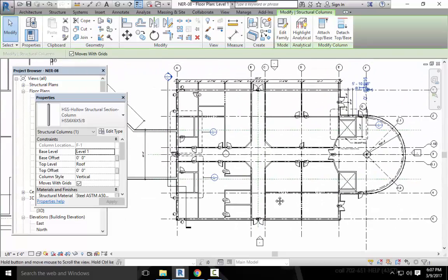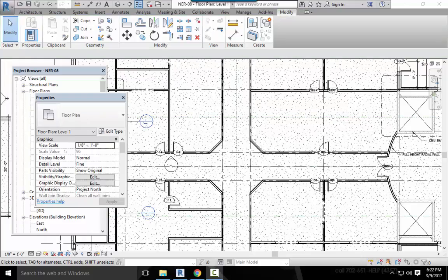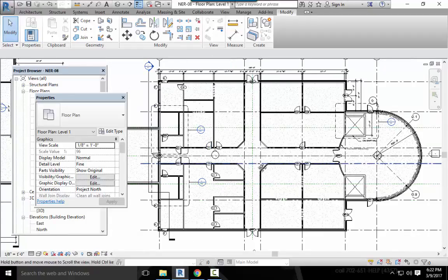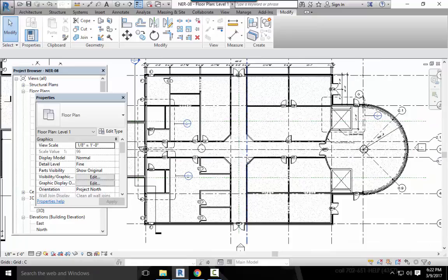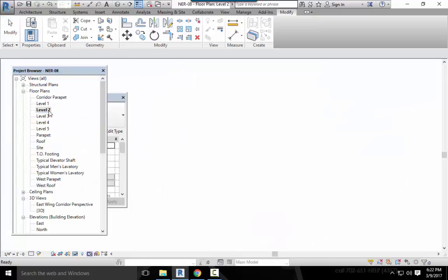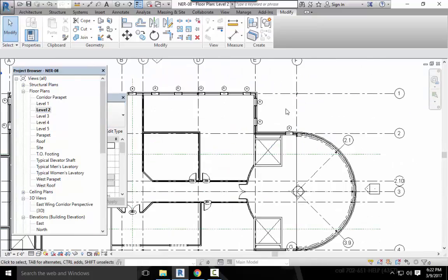And there we are. All right, so the next item is using structural framing. And the architect doesn't create a lot of this structural framing. Normally the structural engineer does. But we're going to create some canopies out over here. Alright. Item 1, in the project browser, go to the level 2 floor plan. It's level 2. Zoom into the radial entry area. Select the columns F1 and F5. These are the columns outside the buildings.